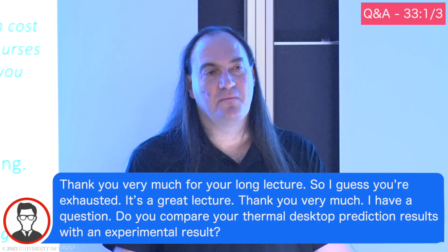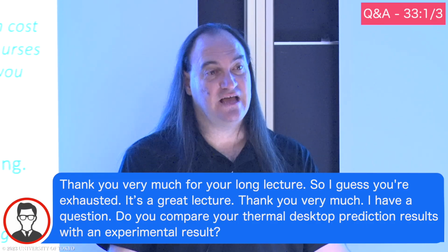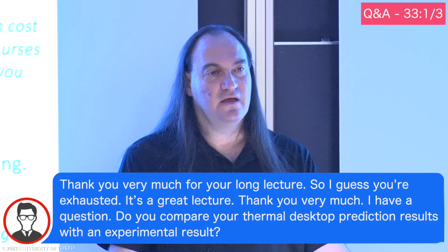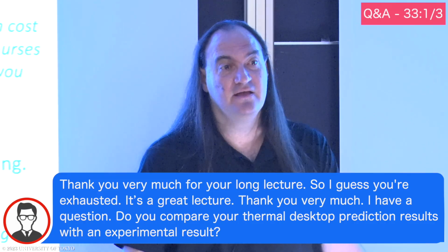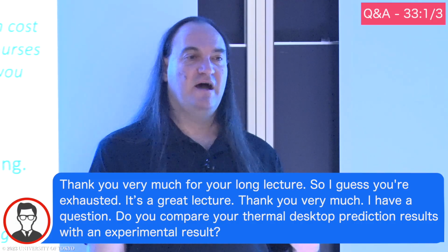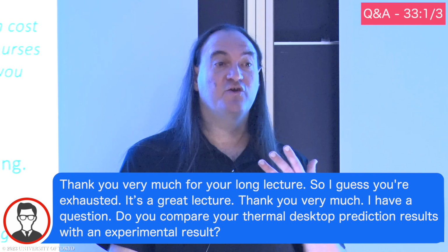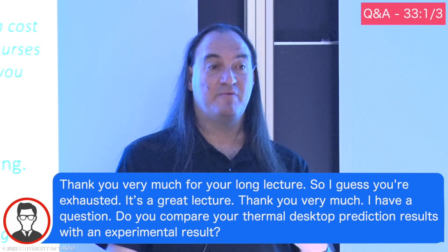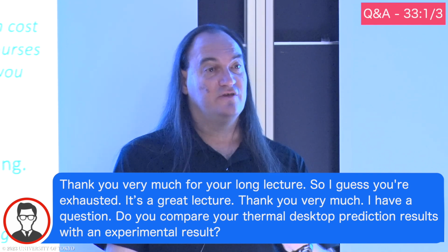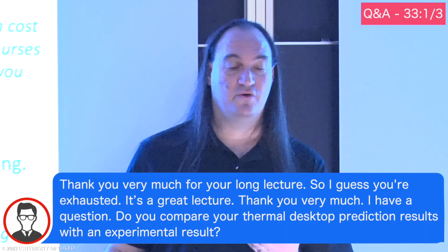So by the time you get to actually having flight hardware, it will go through a testing campaign. It'll be going through EMI, EMC. It might be shock tested. It might be acoustics tested. Certainly vibration, and certainly thermal vac. So the thermal test will have 2 parts.